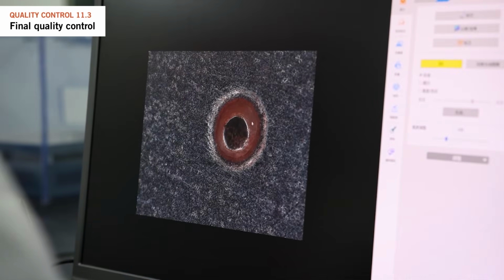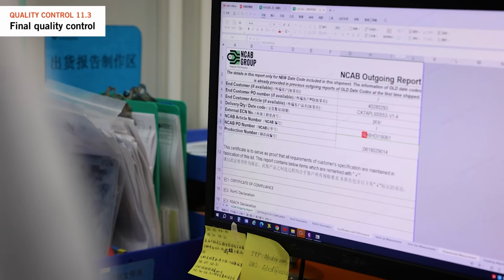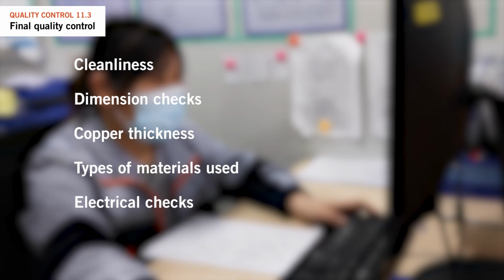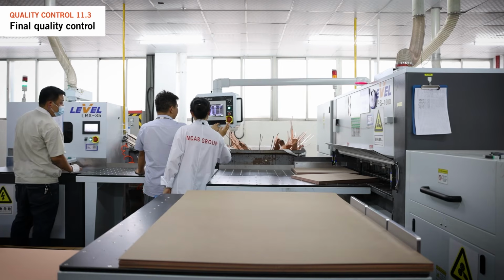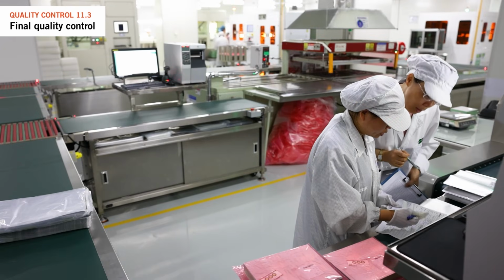To address this, we go beyond and conduct our outgoing inspection report for each new batch. Our report covers various aspects including cleanliness, dimension checks as per the drawing, copper thicknesses measured in over 8 locations, types of materials used, laminates and solder masks, and electrical checks like impedance testing, annular ring size, or BGA pad size. We thoroughly check these aspects to ensure the product meets our standards for a reliable and durable PCB.